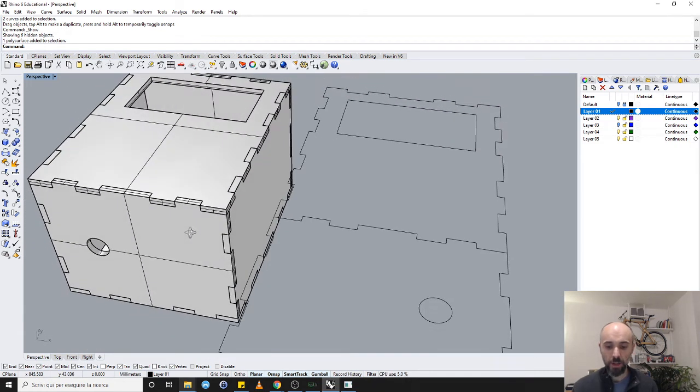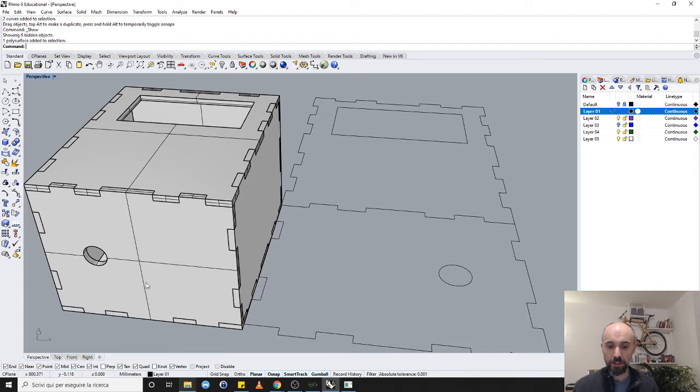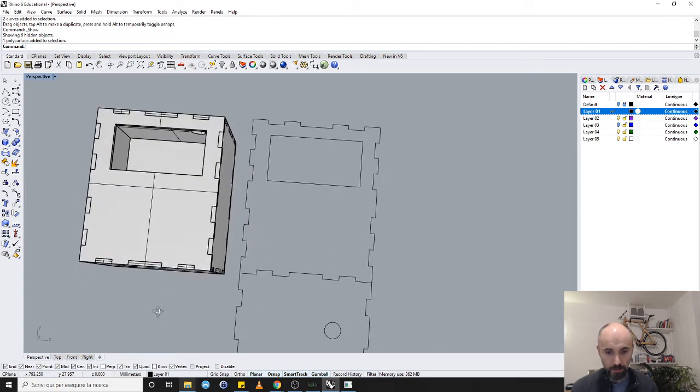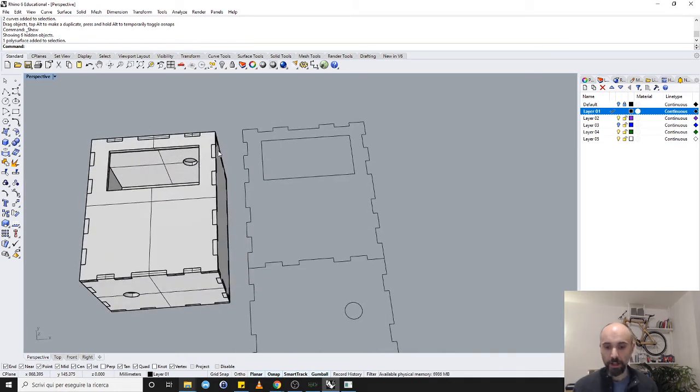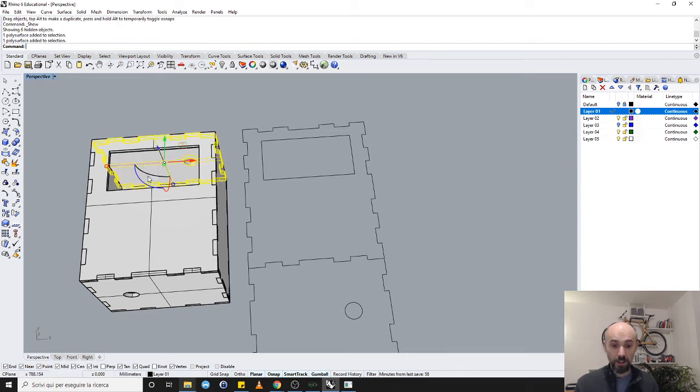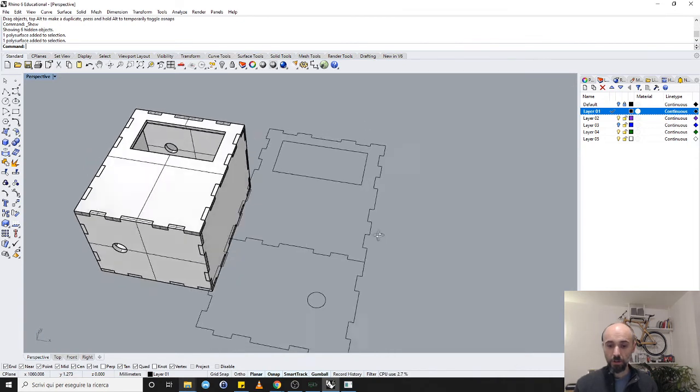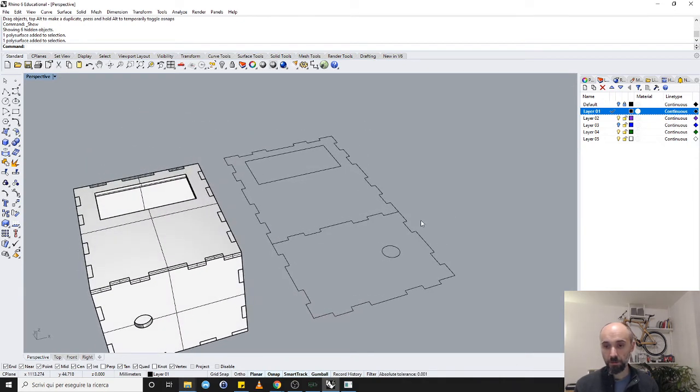So if I allow someone to make something and assemble it the wrong way just because the pieces are symmetrical, I'm definitely not helping out here to make things work. Now the holes are not aligned anymore. If I realize that too late, the object will be already glued together, for instance, or assembled, or even if this is flipped as well 180. Now it looks right, but when I put it together with the rest, it's not going to be anymore. So having symmetrical pieces, as we said, is great as far as they are symmetrical. If you have extra features, you definitely have to change this.